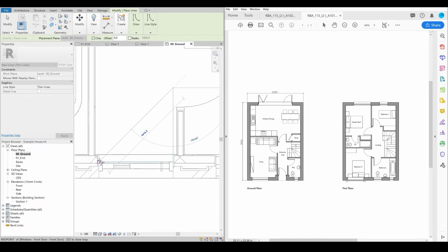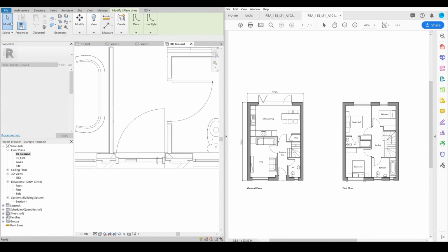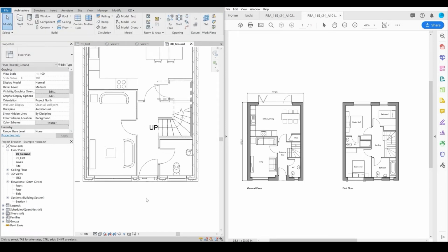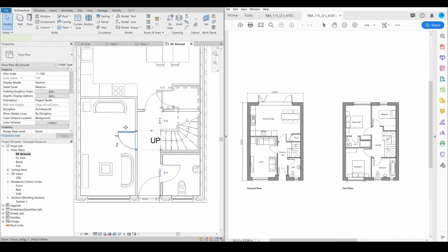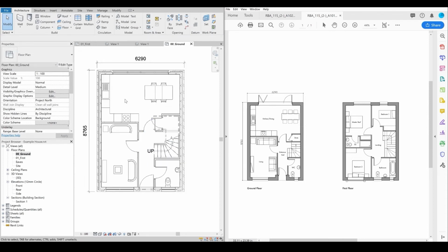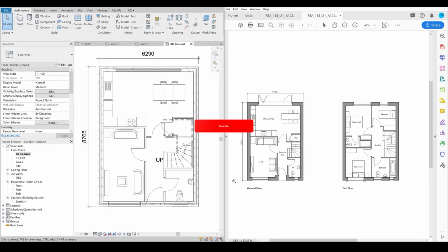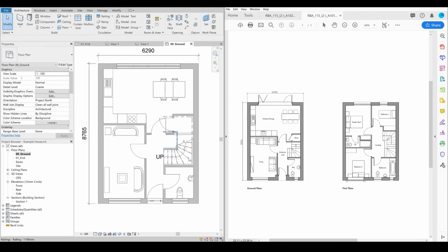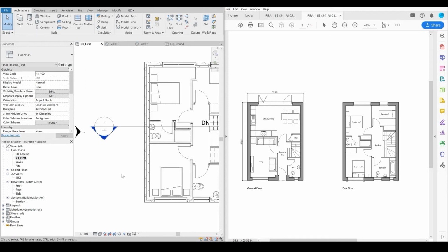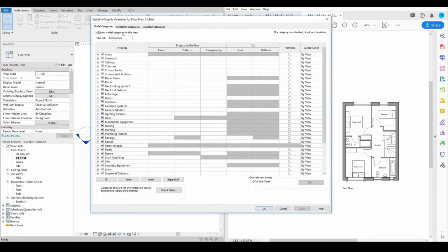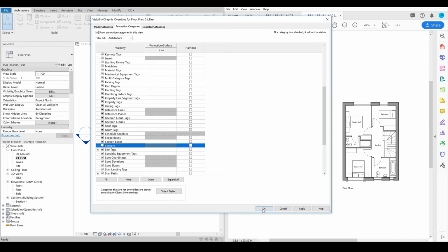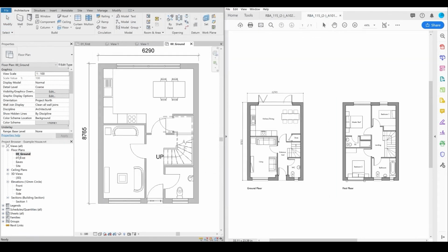So what we're going to just do is just draw the door swinging after the fact, like so. We will go into door families and things like that, but again, as I say, this is very much a 101. Okay, there we are. Now you'll notice that these are plan drawings, so there's not a lot of detail on this. So I would actually just change these to coarse detail, just so we're getting the effect of a plan drawing. Again, we could do that with a view template as well. Take sections off. Okay, nearly done.